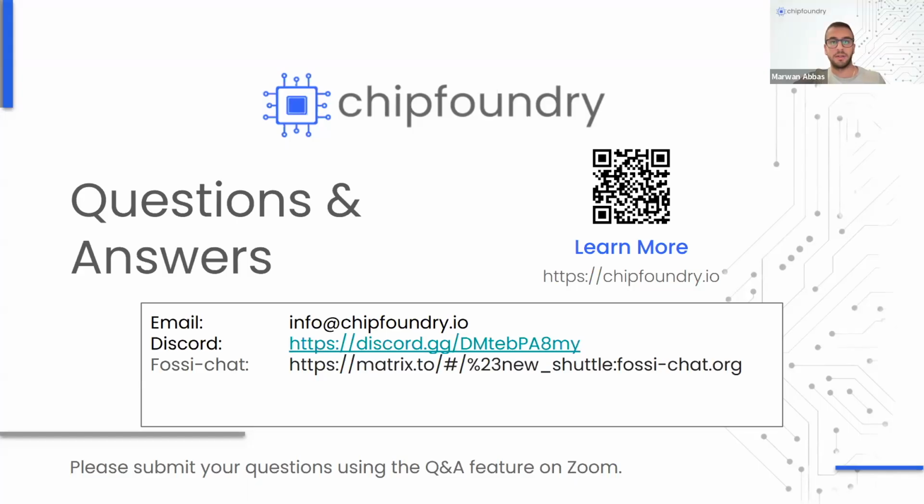And do you have any data on endurance? Sure. Interested customers can just request the data. We have data tested across 20 discrete tape-out chips from Skywater, and each chip had a couple of ReRAM. We have test data at room temperature and at 125 degrees C for retention. So feel free to contact us to request this data. Okay, good, thanks.